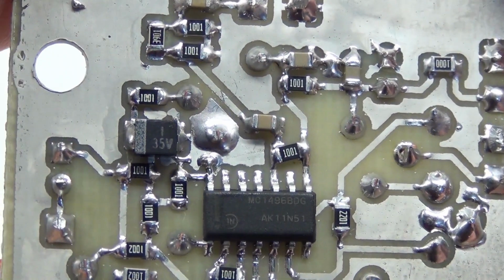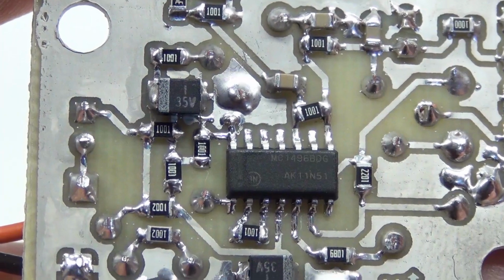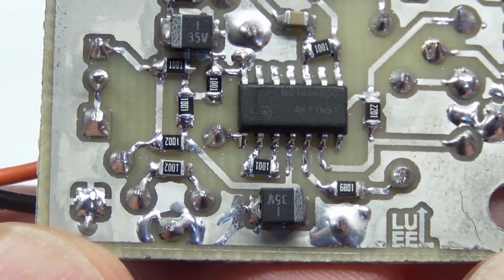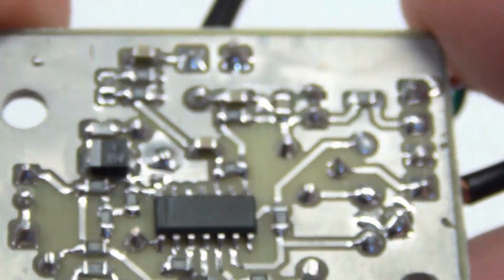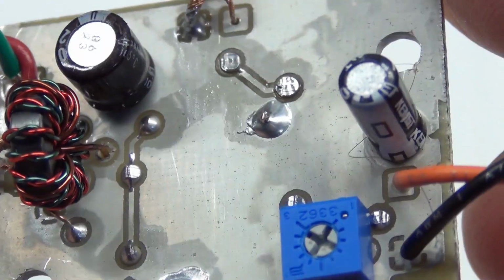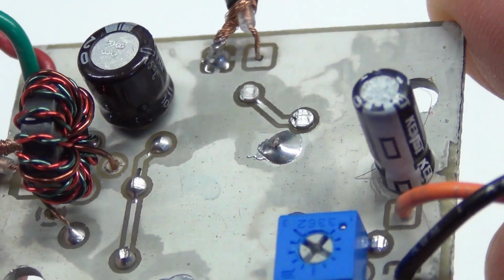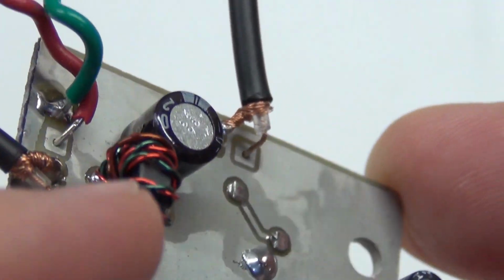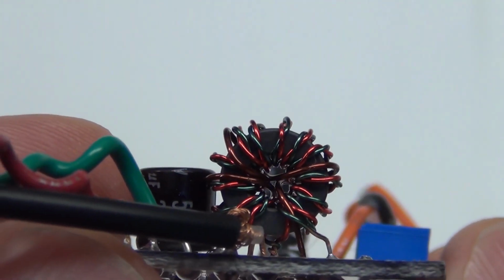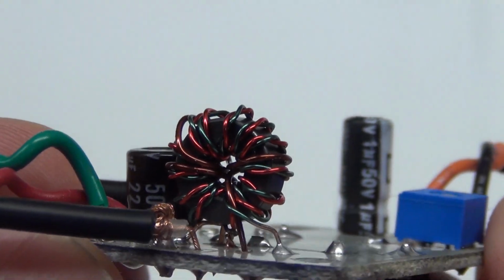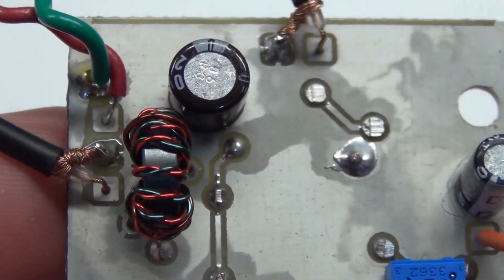I did promise to talk a bit more about the board construction, so let's take a closer look at it now. I'll do a magnified view so we can look at it. So looking at it close up, most of the components, of course, are surface mount, including a couple of tantalum caps. I had 2 at the right value that I just put on there rather than use leaded electrolytics. But speaking of electrolytics, on the other side, there's 2 electrolytics there, the trimmer pot for the carrier balance, and then there's that little tricky transformer I had to wind. It's got a bifilar primary and then a simple secondary, so getting all that stuff crammed in through that small FT37-43 core was a bit tricky.